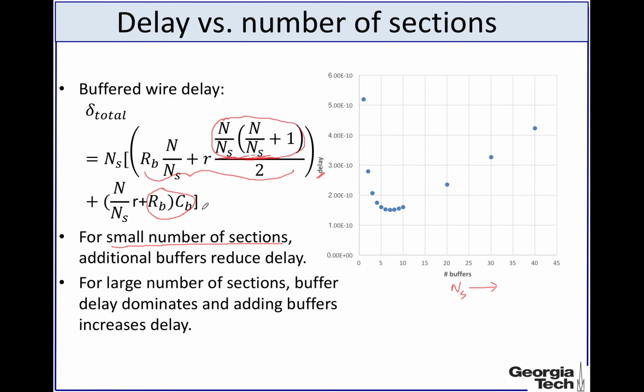But beyond a certain number, or a bit beyond a critical number of buffers, increasing the number of segments does not decrease your delay, rather it increases it, because the buffer delay then dominates, and that's that.